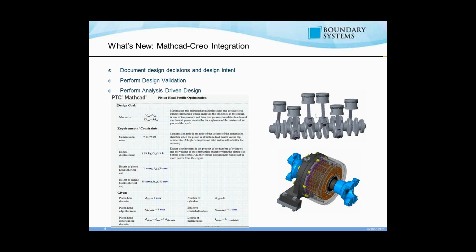Another huge benefit, which I know that I usually benefit from, and I know a couple of people have mentioned as well, is that for long-time Creo users or Pro Engineer users, you'll know that the relations box inside of Creo is not so user-friendly. It's typically clunky at best. So instead of typing equations into the relations editor and wondering if I did it well and keeping my fingers crossed, I can just put those into Mathcad.